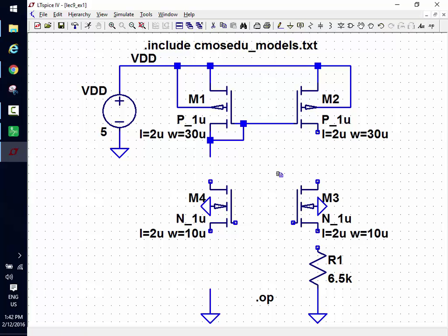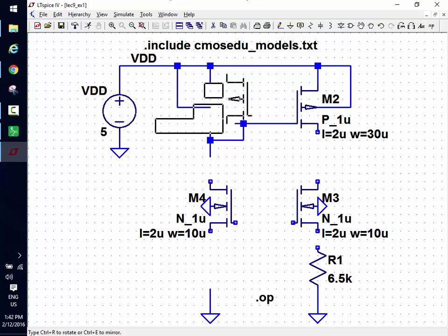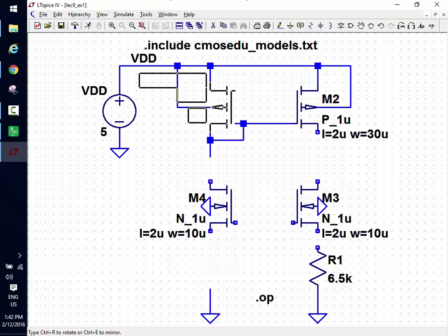One thing though that I think I'm gonna do, it's a little bit trivial, but I'm gonna do it anyway, is move the source so that it's in the right position. You see the source is this node, the one the gate is closest to. So the source is here. When you look at the netlist and you see drain gate source, it lines up correctly.